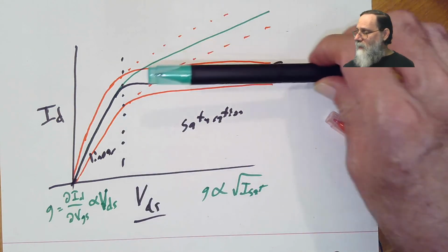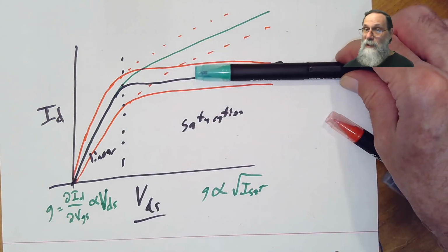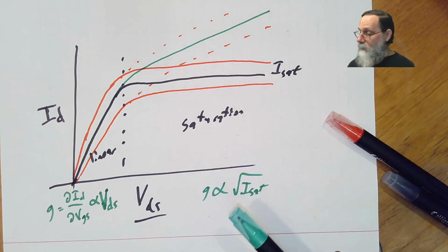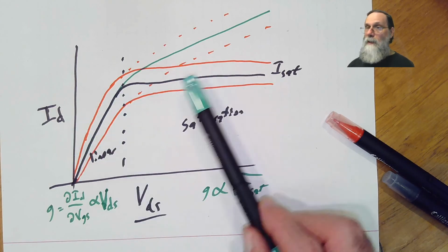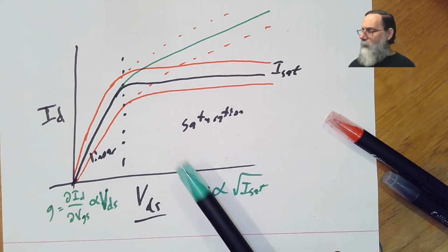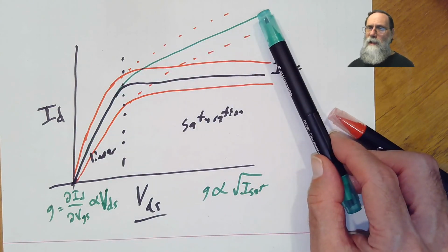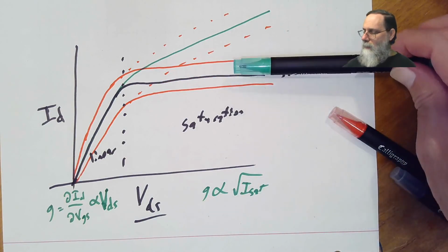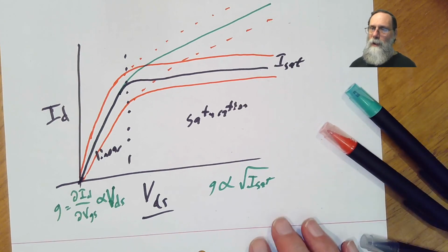Of course, that's based on a model that assumes the saturation current is constant, because it does go up somewhat with voltage, we do get some change as we move out here, and I believe it actually gets slightly more sensitive as we increase the drain to source voltage rather than remaining constant, the way the simple models say.